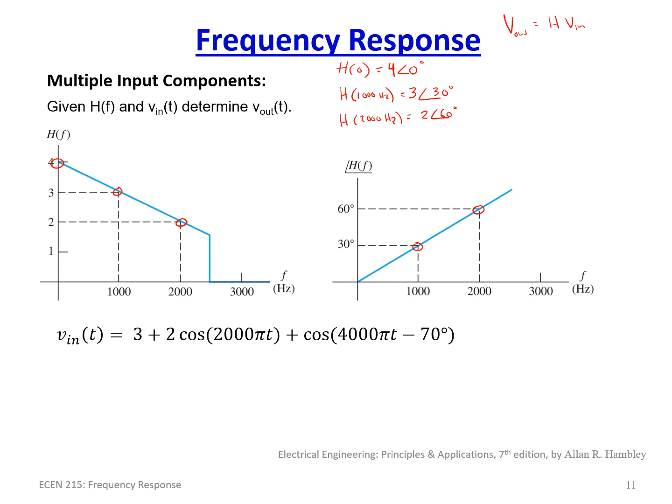And of course at this point, our V in at 0, the DC component is the 3, so that's just 3, and there is no phase. I mean, this is just 3 DC. So that will be simply 3 times 4. Then we have V in at 1000 hertz.